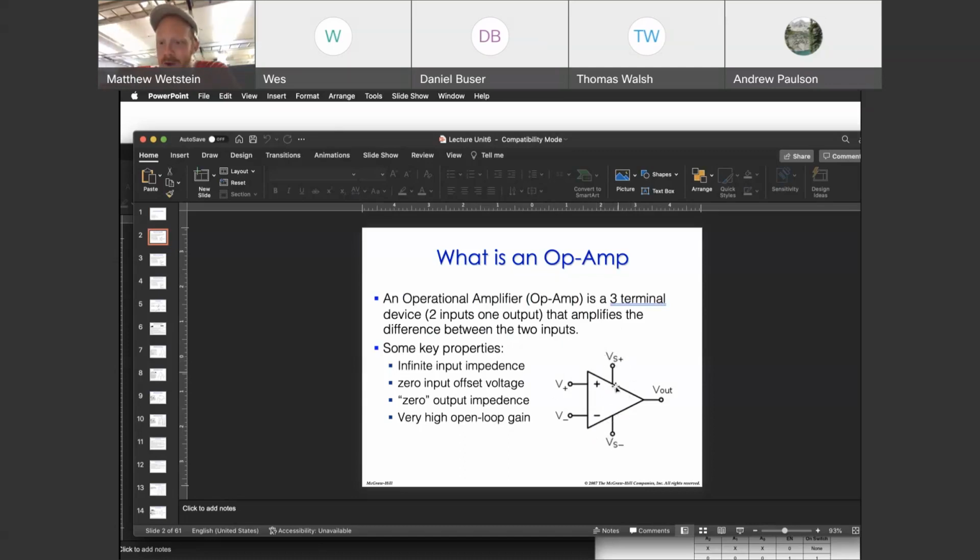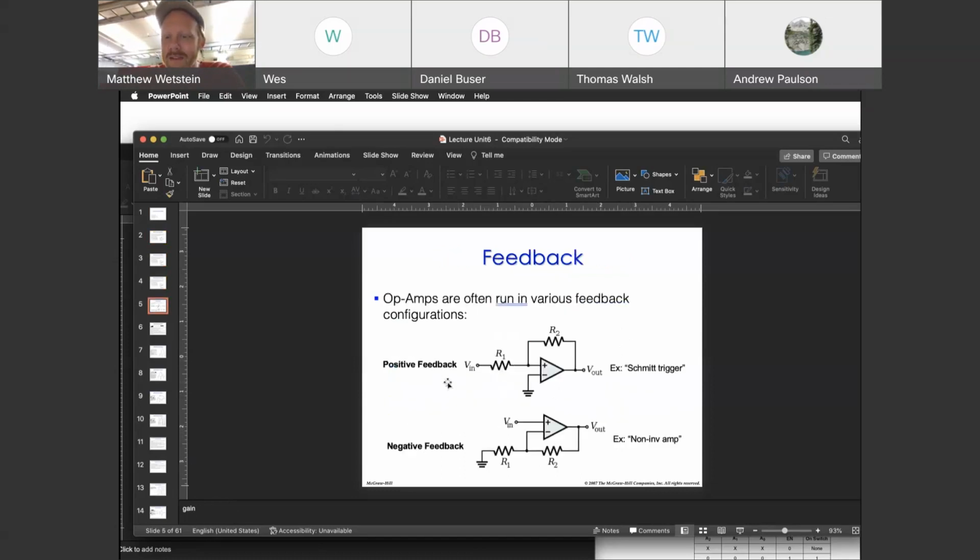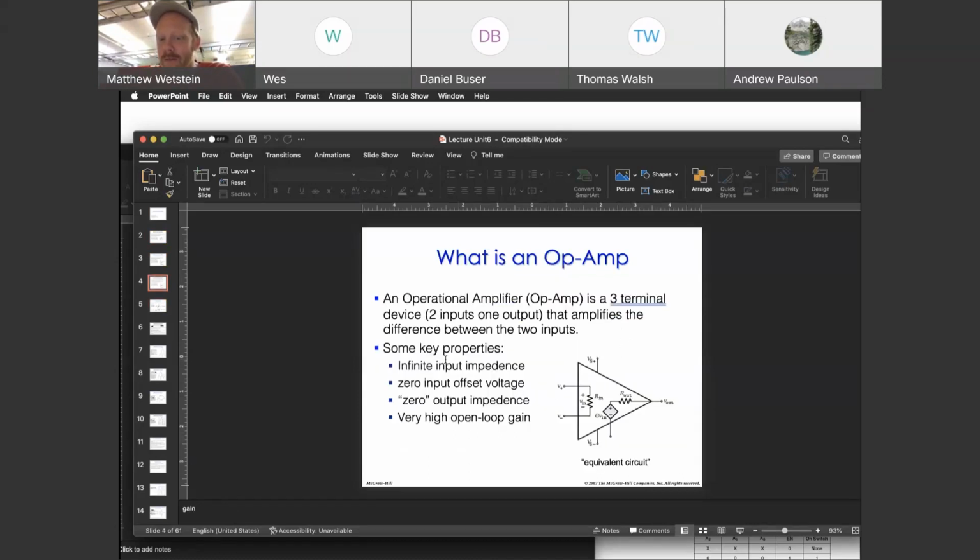And so the 2 other pins are your plus and minus. You'll also note that in some op-amp chips, you also need to tie a pin to ground, et cetera. Know the key properties of op-amps, know how to compute gains. So, know that an op-amp amplifies a small differential signal.